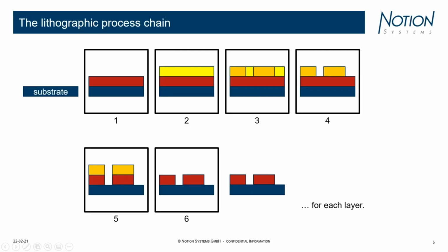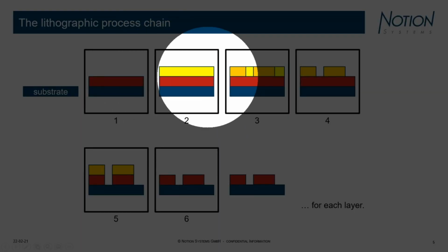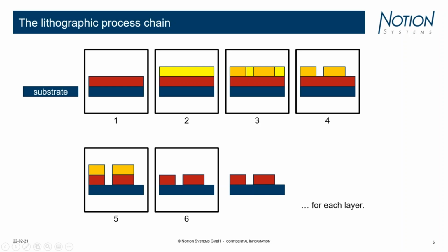This can be a vacuum coating, this can be a slot die coating, even a dip coating, or any other technology, but it's always full area. Then in the second process, you apply an etch resist, typically with spin coating or with dip coating, sometimes even full area screen print.